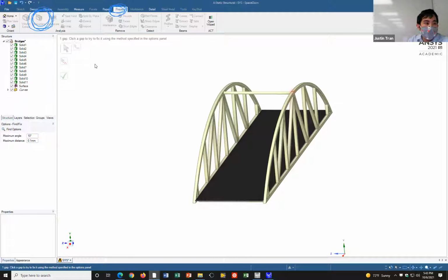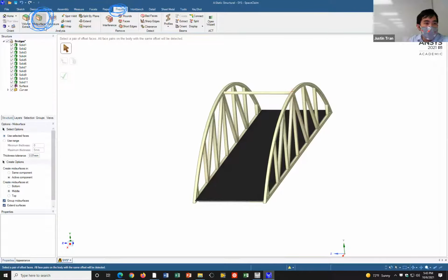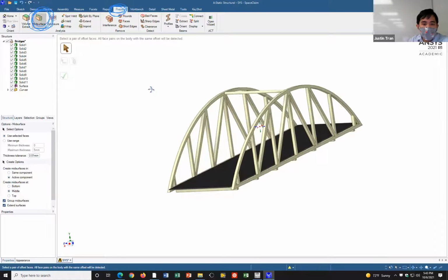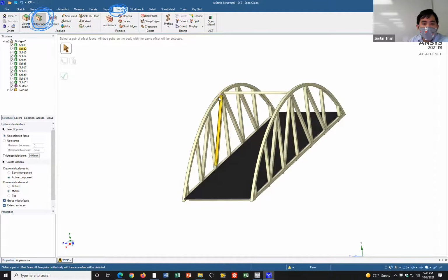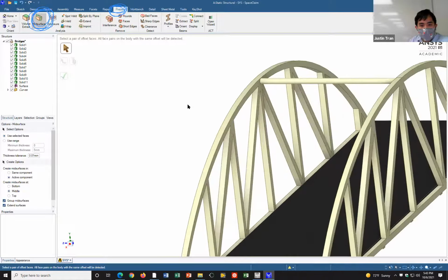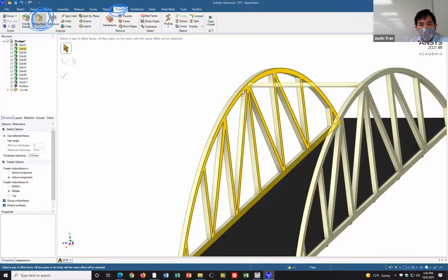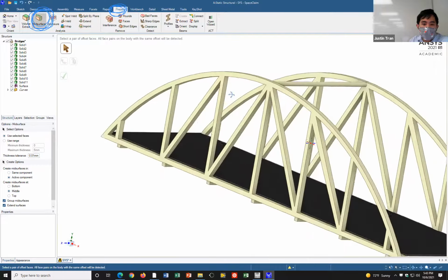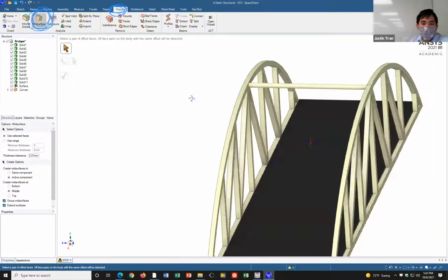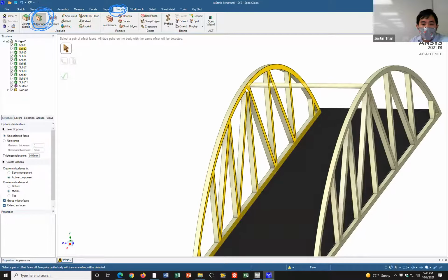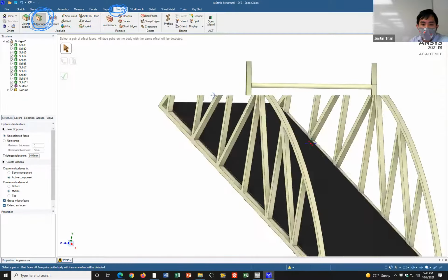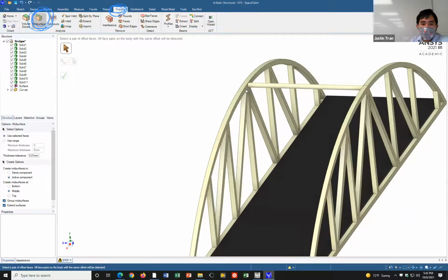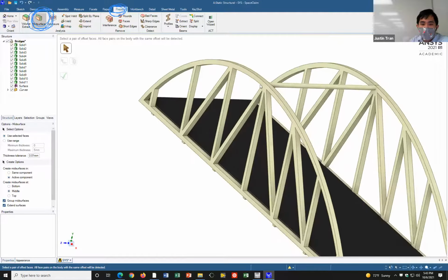All right, so let's go ahead and click the Mid-Surface tool right here. And then let's start by making a mid-surface of the two sides of the bridge. Okay. And so the way this works is that you're first going to click on one of the parallel surfaces. And remember, in order for a mid-surface to work, it has to be two surfaces that are completely parallel to each other. The two surfaces I'm going to pick are the inner side of the bridge. And so I'm going to click it. After you click it, it's going to highlight for a second, and then it's going to disappear. Okay. Then I'm going to click the other side of the bridge.